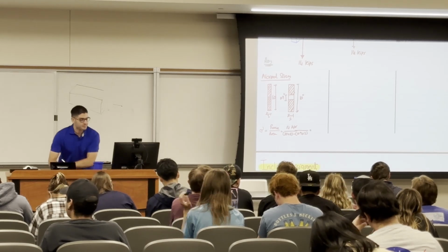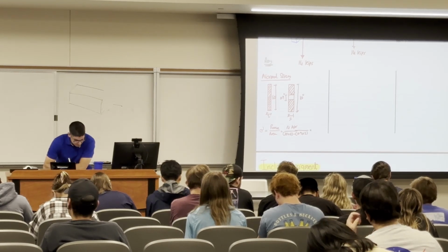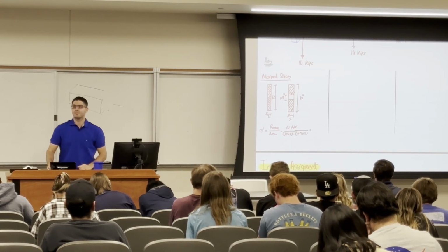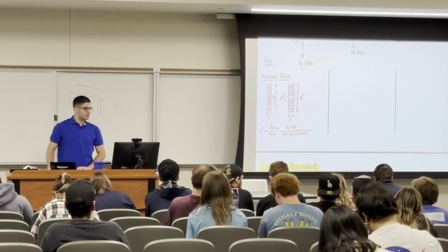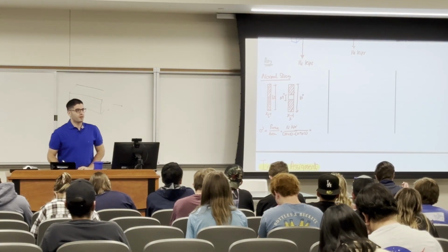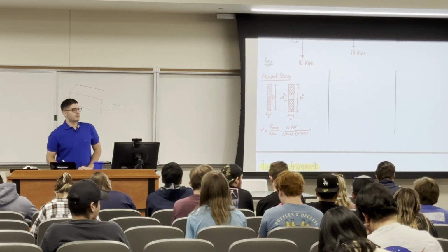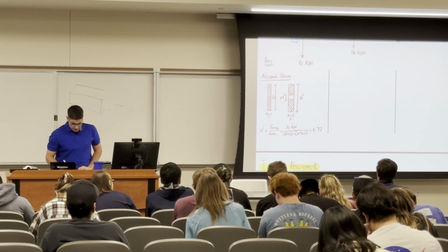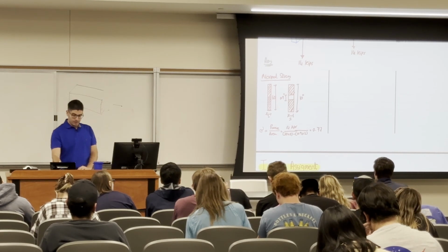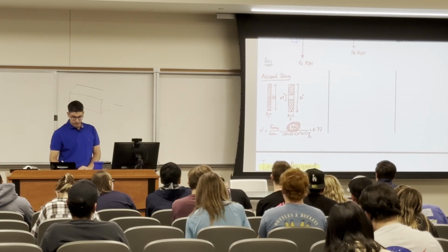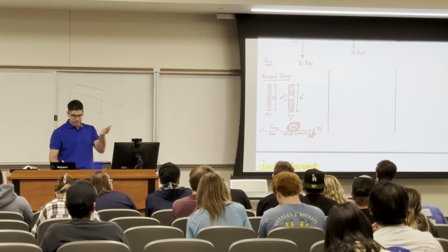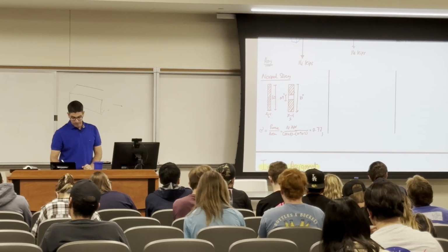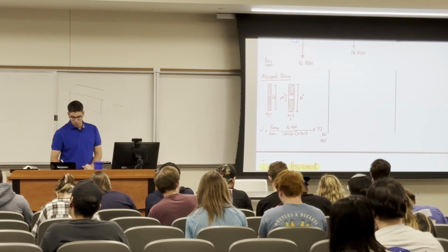Anyone? Anyone agrees with him? Okay, 0.79, 0.77. What are the units here? I have kips on top, and I have area, which is inches squared, on the bottom. So what are the units? KSI. Or someone might write kips over inches squared.